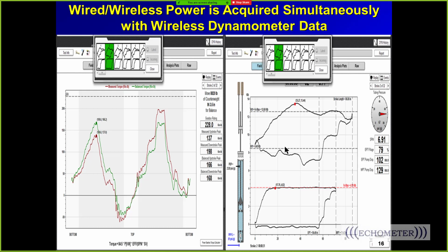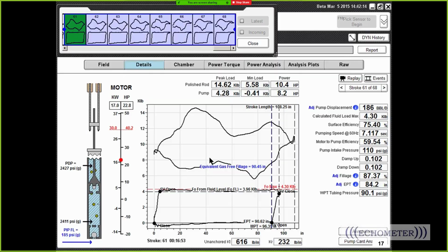If your well is going to operate with the pump off controller and basically be full, then you would position weights on the full card. If you're going to operate on hand and the pump won't be full, then you need to position the weights based on the pump card not being full. All right, so that's what this is trying to show here.